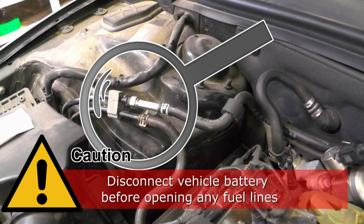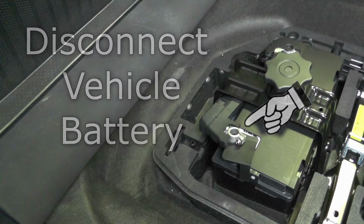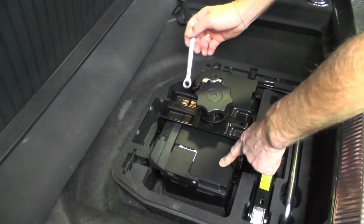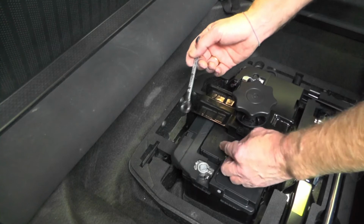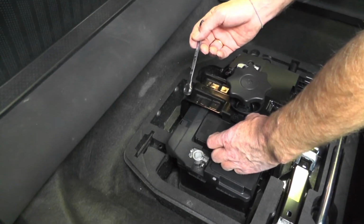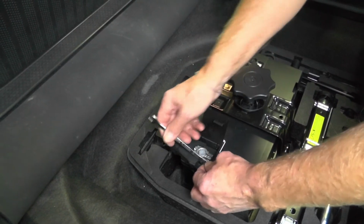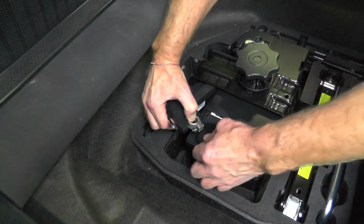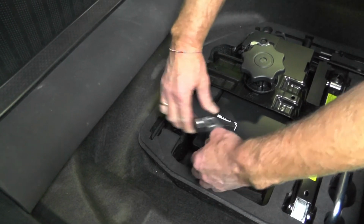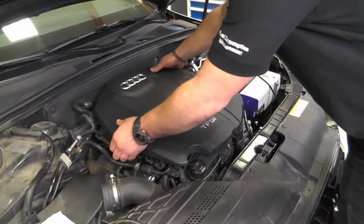But before continuing with mounting the fuel lines, we are going to disconnect the vehicle battery. For safety reasons we are going to disconnect the battery, as the fuel supply pump may start to pump as soon as we open the line and pressure goes down. So we disconnect the plus pole of the battery. For safety. So now we are ready to connect the fuel lines.